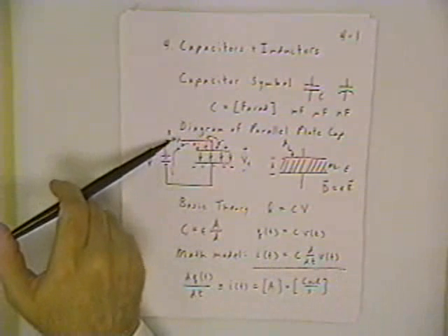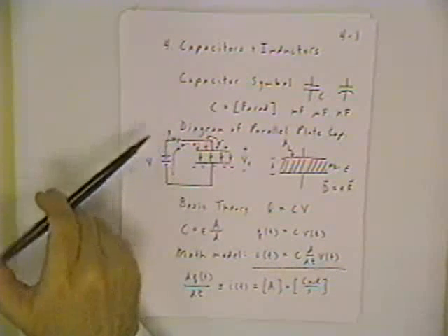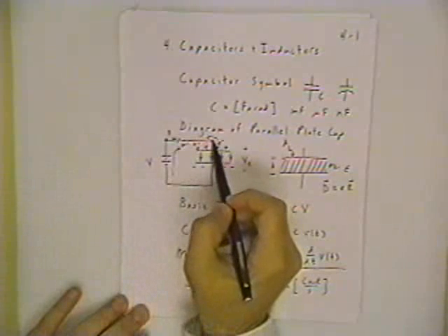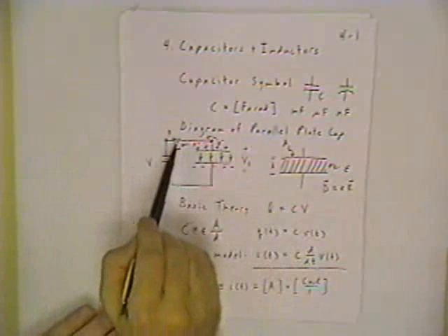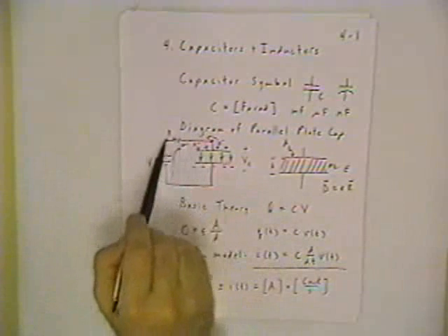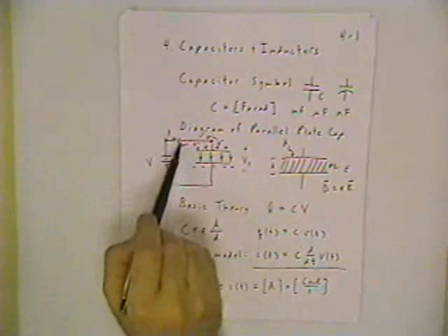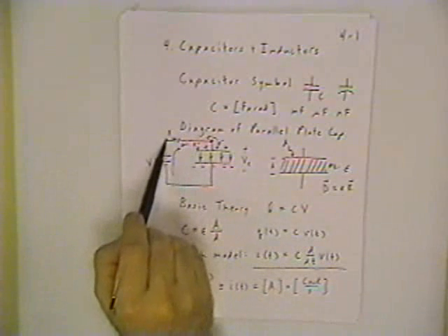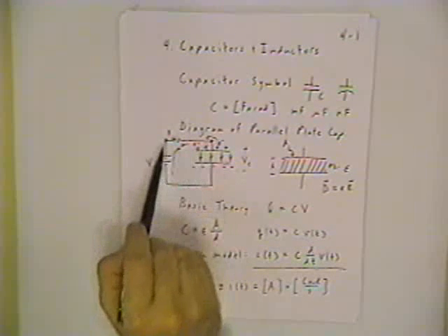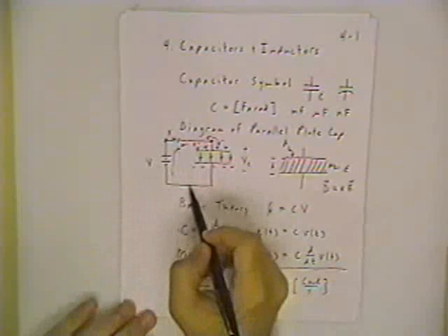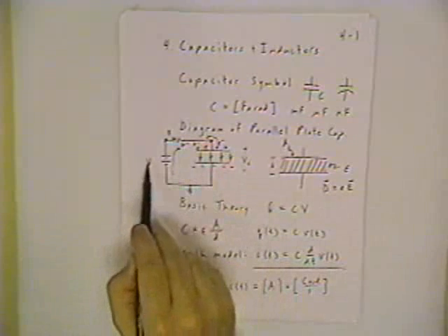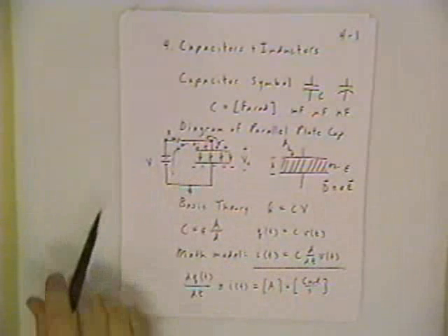And that matches up intuitively with what we have up here with the charging capacitor. The only way this resistor has any current flowing through it is if there's a potential difference across it. So comparing this node and this node in the circuit, if that potential difference is 0, there'll be no more current. And if that current is 0, then the voltage at this node is equal to the voltage at that node. They're both equal to V. And that shows that with respect to the ground node here, the capacitor has fully charged to V volts.